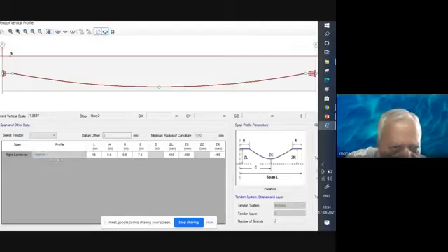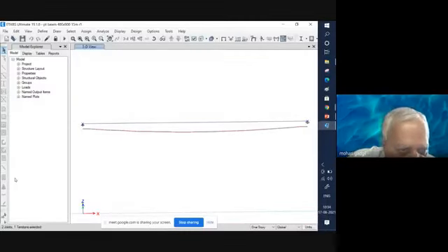You can see that for this curve there are various options, which I think right now are not highlighted because I have a run model. There are several curves indicated, but parabola is most popular, so we have taken parabola as a curve. Accordingly you can consider the cable profile as parabola with these coordinates at the end points, 450 from top at the left and right support and 800 from top at the midspan. Okay. Now you consider this as the cable profile.